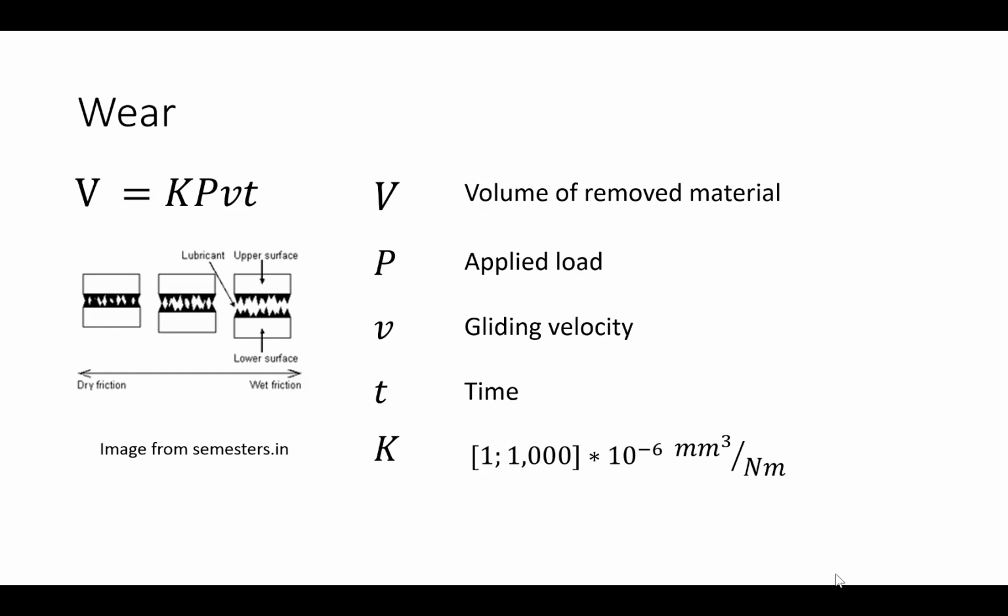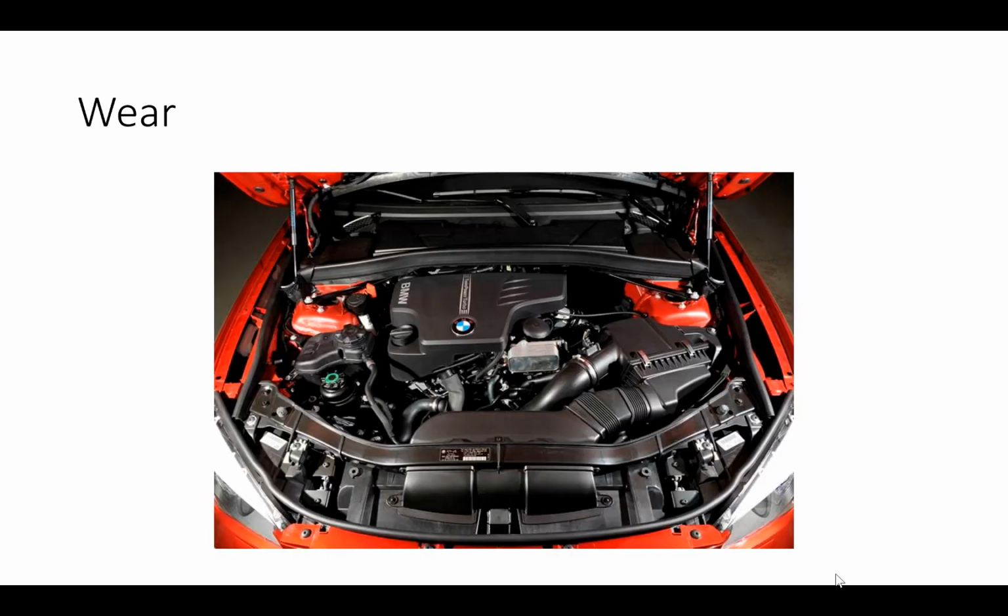Wear is often highest when 2 parts are initially brought together, and this is called the run-in period. You may have heard this when it comes to driving a new car, for instance. But after the running period, the wear declines significantly, and we say that the 2 surfaces have adapted to each other. Wear interferes with machine operations by increasing the tolerance of parts, or this is also called rattling.